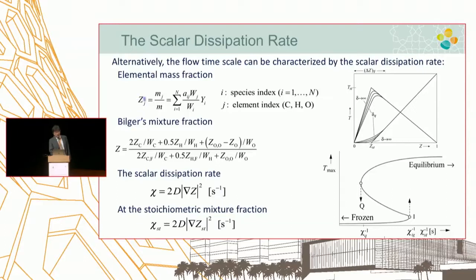In fact, the real mixture fraction is typically defined in Bilger's way, in order to allow for the fact that different species move differently due to different diffusion. It's not a rigorous derivation, it's an empirical compromise to account for that between C, H, and O elemental mass fraction. If you compute elemental mass fractions out of your flame calculation, you will find they are all slightly different.